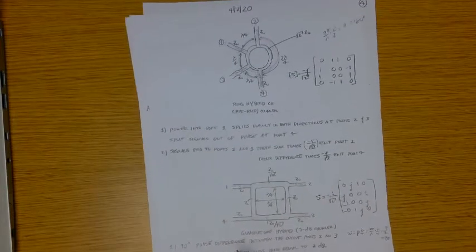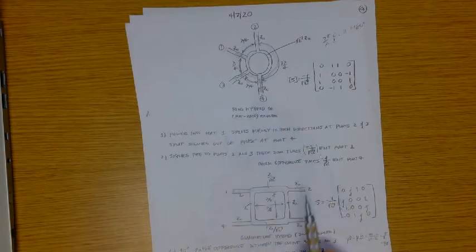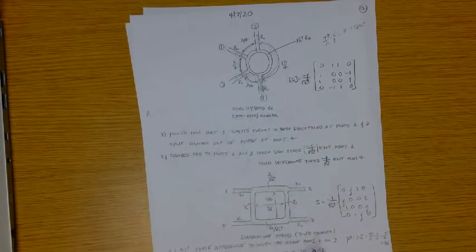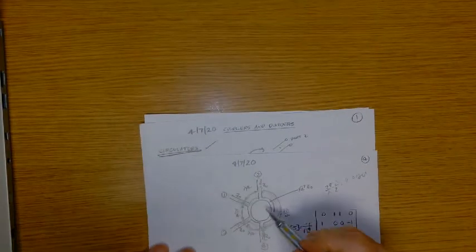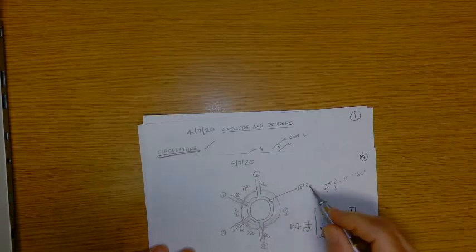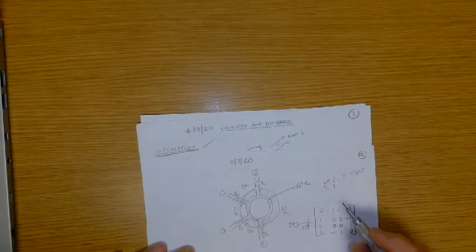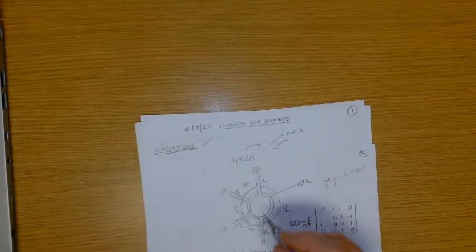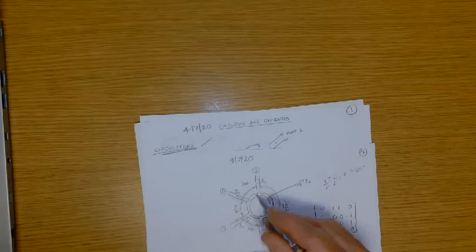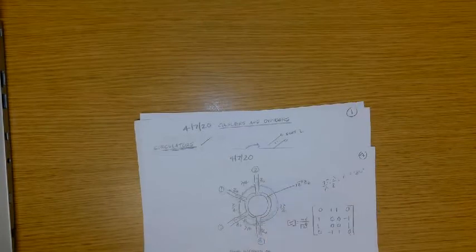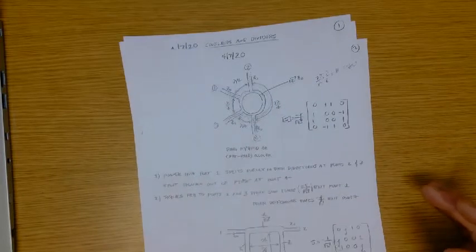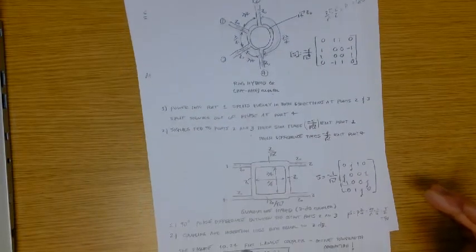Okay, so that's one manifestation. Here's another, right? Here's a quadrature hybrid or 3 dB coupler. So note back up here though, right? This impedance is the square root of 2 times Z naught, whereas the impedance of the feed lines is Z naught. So if this were in microstrip, we'd have to modify the width of the rat race compared to the width of the feed lines. Okay. Again, this thing would have some bandwidth characteristics that would have to be characterized as well.